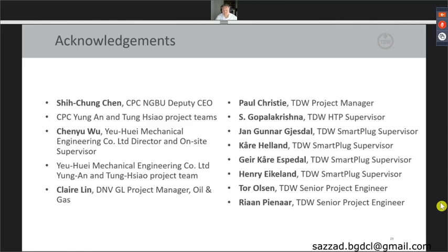From Mr. Fazlal Karim, between the two types of isolation system, which is better? That all depends on the application. We cannot say that one is better than the other, and it depends really on the application that you have. So if you have, for example, a line that has never been pigged before, and you know the restriction in the line, you don't have a choice.